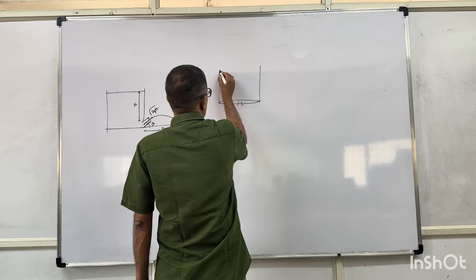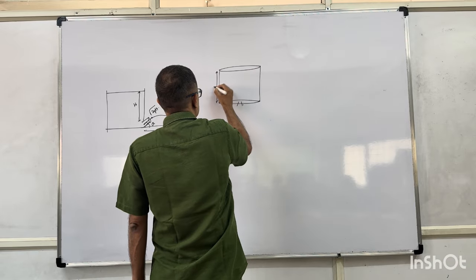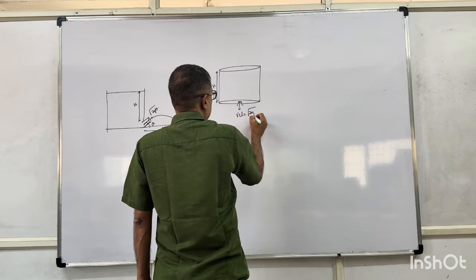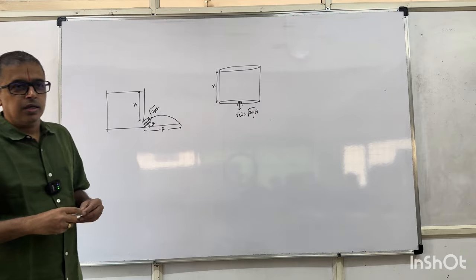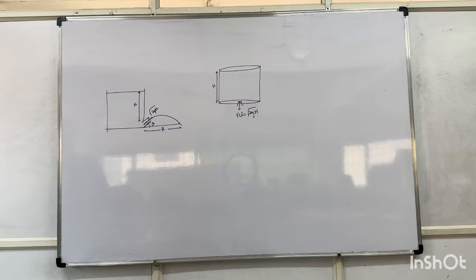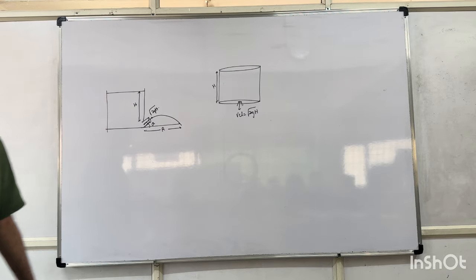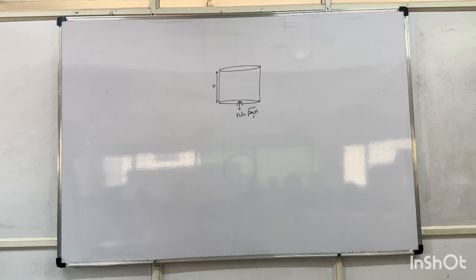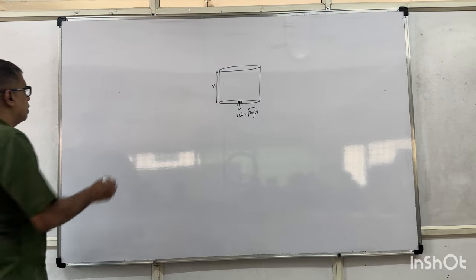What if the container has a hole underneath? Matters not. This will also have velocity root over of 2gh. Instead of a hole on the side, you can have a hole underneath. It doesn't matter. It will be root 2gh. It will be in any direction. You have this.